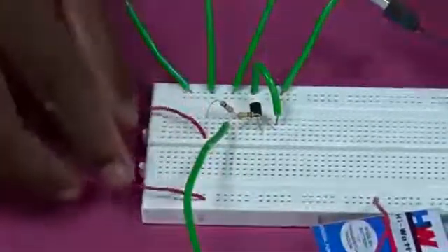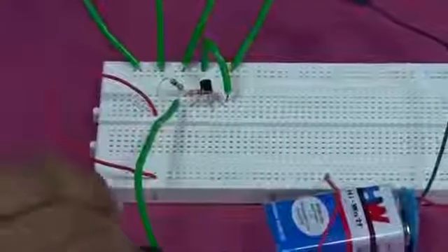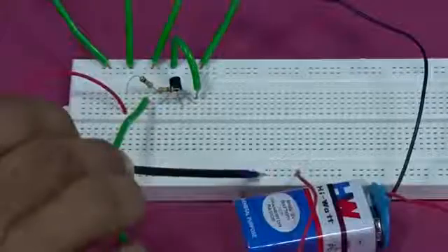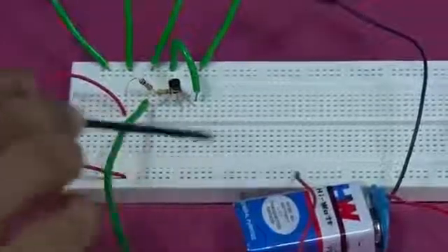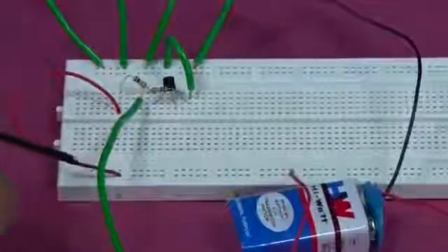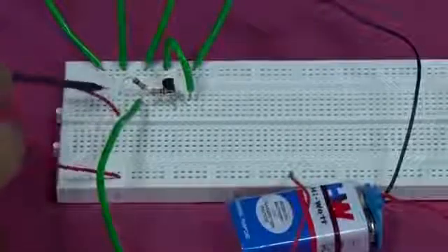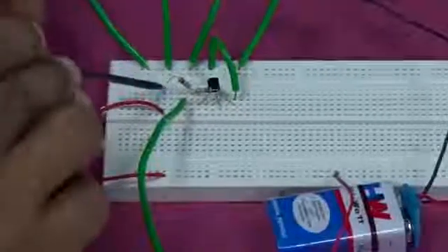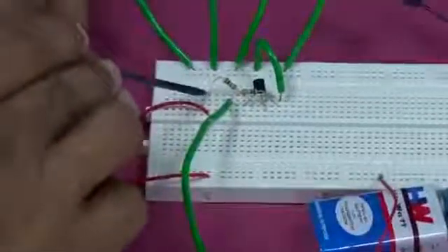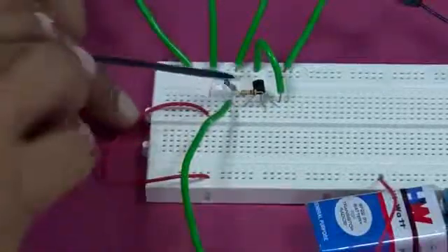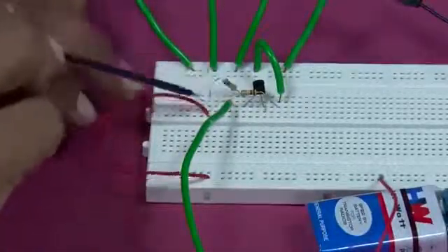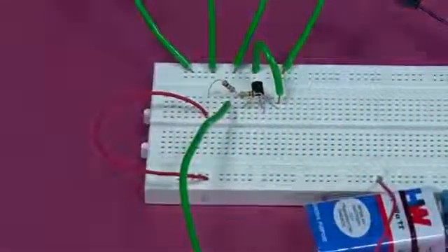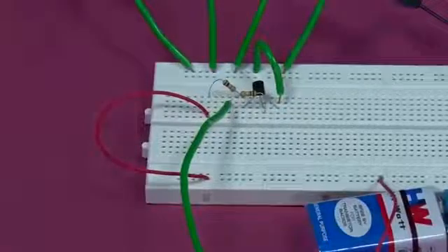Very good. So, you understand the working of the breadboard. This positive of the battery is joined here, but these are all internally connected. So, that 9 volt which is here is also coming here, and from here I am going to this point, and these ones are internally connected. So, this 9 volt has been connected to the other end of the resistance. One end of the resistor is already connected to the collector. That part is done. The negative of the battery is already at ground. So, our output side is also complete.